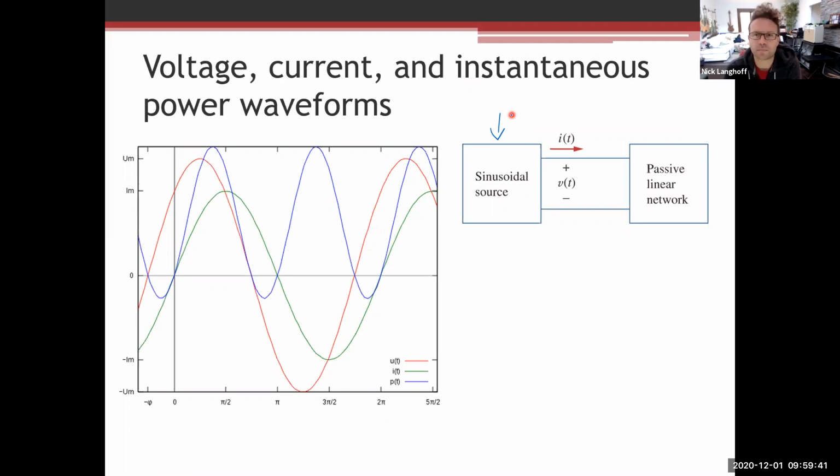Those things are highly inductive, and they in fact can interact with the power grid in your house and create inductive, let's just call it noise, for lack of a better term. And those can couple into the power supply and everything that you're powering.